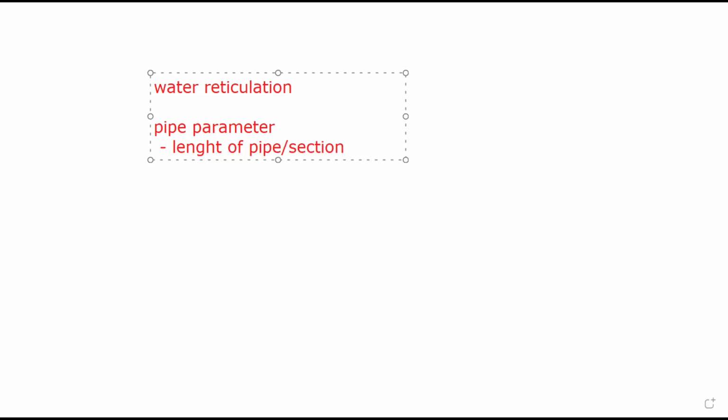So assuming I'm coming from Aminu Kano to Ademola Tokunbo, that is the 2 junctions. So from junction 1 to junction B, what is the length of the pipe? I need that length because with that length I calculate my losses, my velocity, and many other parameters. Then the second pipe parameter you need is what is the diameter?